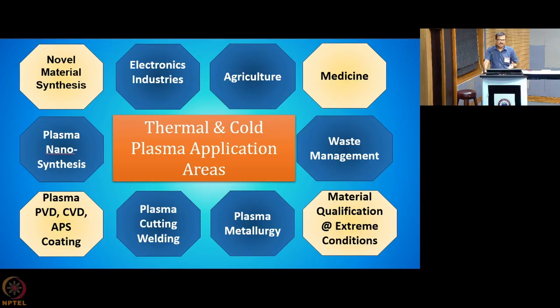Basically the rare earth can protect the material from highly reactive substances like molten uranium. So, you can coat that crucible using, say, yttrium oxide or some rare earth oxide to protect the material of the container from reacting with the molten uranium. So, there are certain applications where this novel nature of this kind of coating is extremely useful.